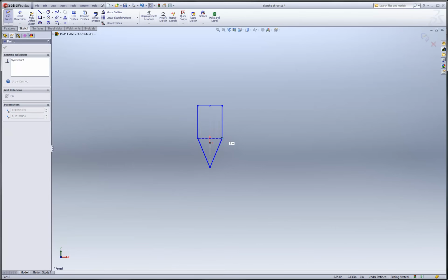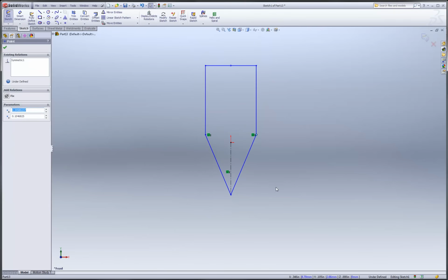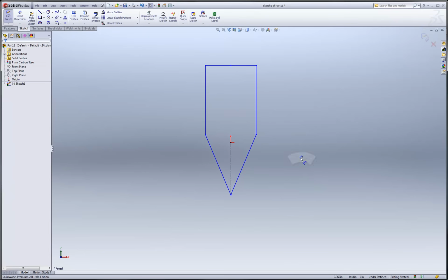I'll drag on that shape just a little bit to make sure that the sketch relationships behave as I intend. I want to leave a little bit of space above the origin so that the profile has a little bit of air up above it, which will assist in helping features rebuild a little bit quicker and making them more predictable. Now let's apply some dimensions.